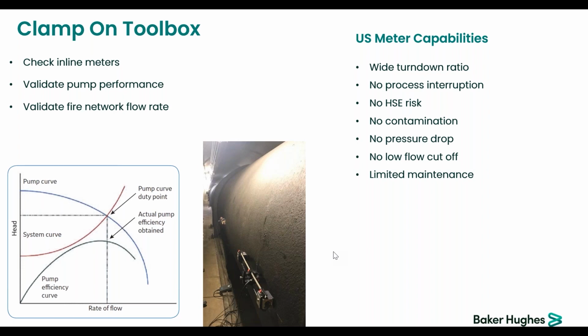If you have a bit of debris or buildup inside of the pipe, it will certainly create a slight error on your volumetric flow rates, not really on the velocity per se, but on the volumetric flow rate, because remember, you multiply the velocity times the cross section of the pipe. So if the cross section is not what is reflected, it will be difficult.